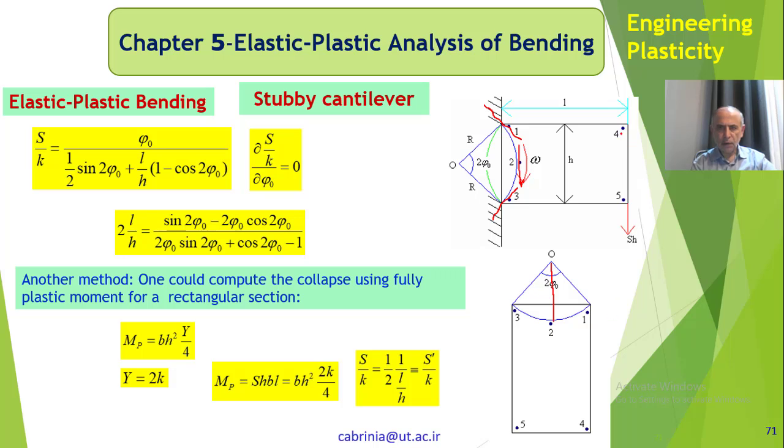So what is the velocity of point 4? Obviously 4 remains the same relative to 1. So if we put a line like that, 4 and 1 remain the same, 3 and 4 also, 3 and 5 also remain the same. Okay, so that's how we obtain the hodograph. That's the hodograph. Okay, the velocity at any point is known. This point, or any other point in here, we know the velocity using this hodograph.